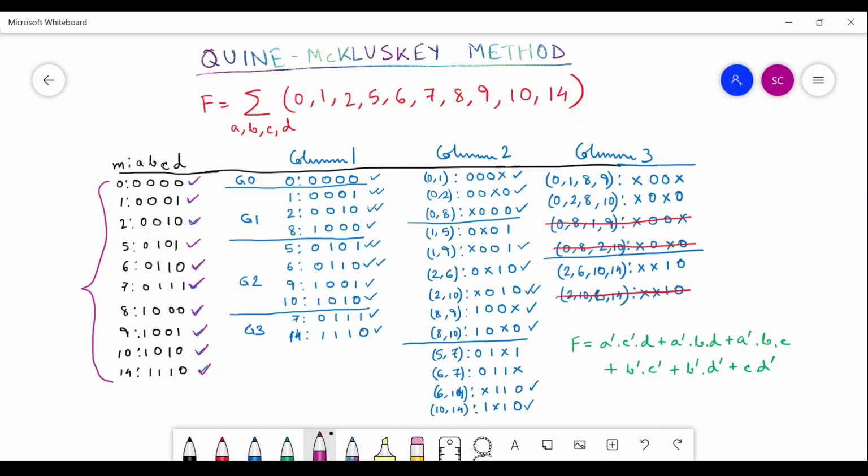Remember that all these minterms are giving you an output of 1. However, out of those, these two are adjacent inputs. So that means that when you write them together, the bit which is changing can be omitted. So that is the beauty now. If you club these two together, the bit which is changing can be omitted. So that is what we will exactly do.